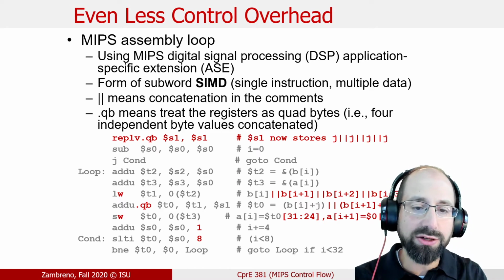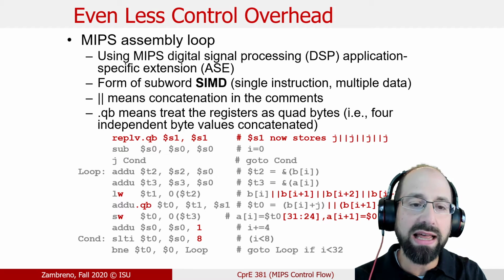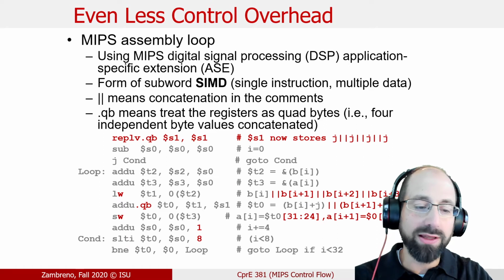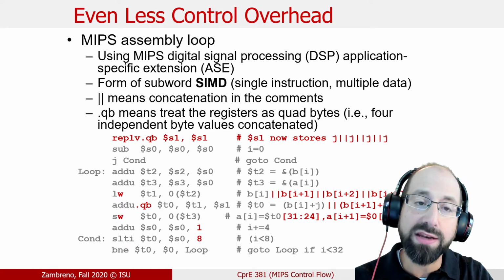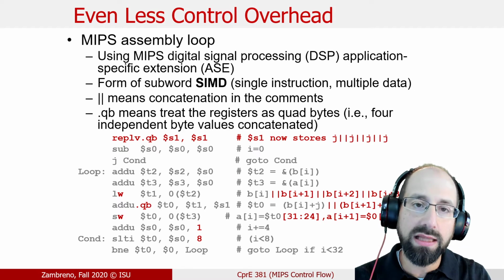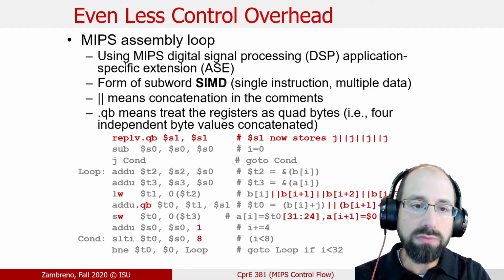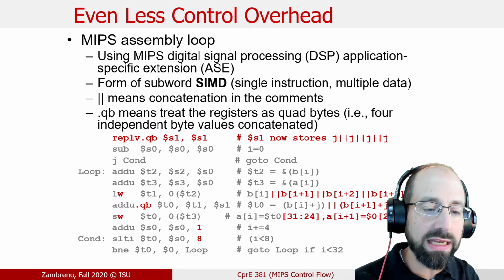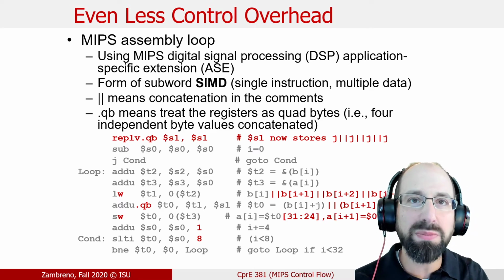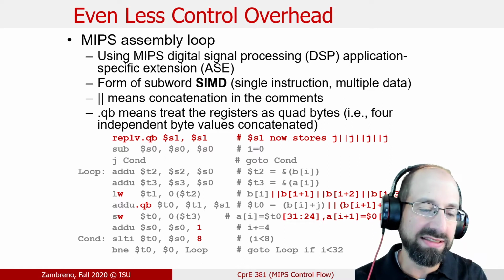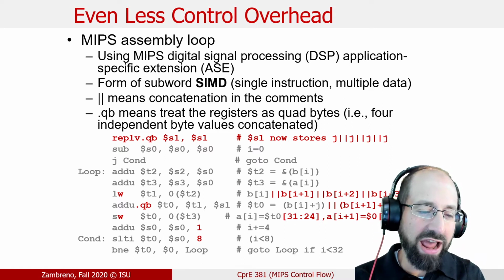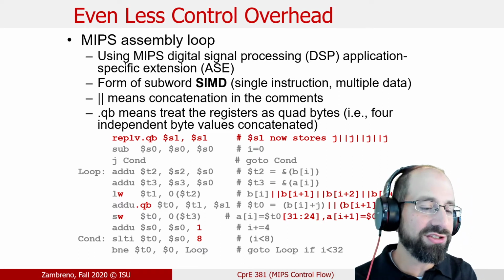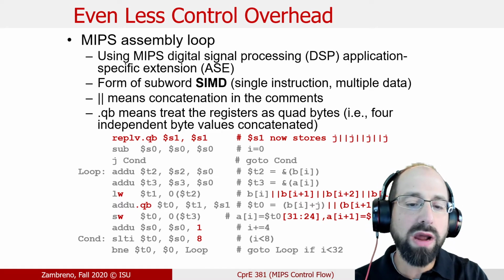But typically, a processor can be categorized by what subsets of ISAs it supports. And for MIPS so far, we've just been supporting MIPS, and we've just been calling it the MIPS32 ISA, and that is correct and that is true. But what I'm saying is that MIPS, like almost all other ISAs, also has these defined extensions. MIPS refers to them as application-specific extensions, and they refer to this one as their DSP, or digital signal processing extensions. The naming for these extensions is half marketing and half technical. There's nothing really specifically digital signal processing about these extensions, but they're a way of extracting parallelism out.